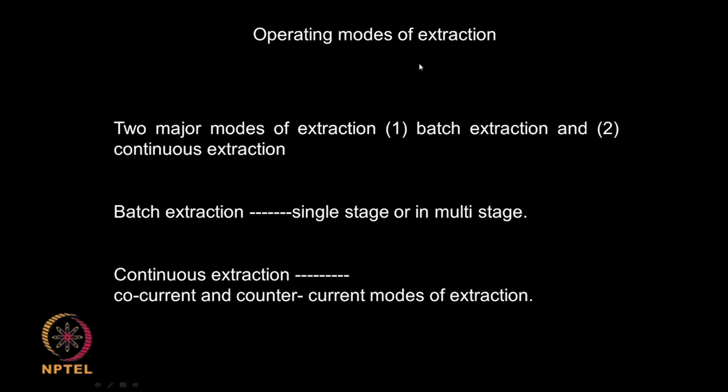So, the operating mode of this extraction could be batch or continuous. The batch extraction could be single stage or multi-stage, and continuous could be co-current or counter current. In the single stage you may be adding fresh solvent, and in multi-stage also you may be adding fresh solvent. We will look at each one of them a little more in detail.